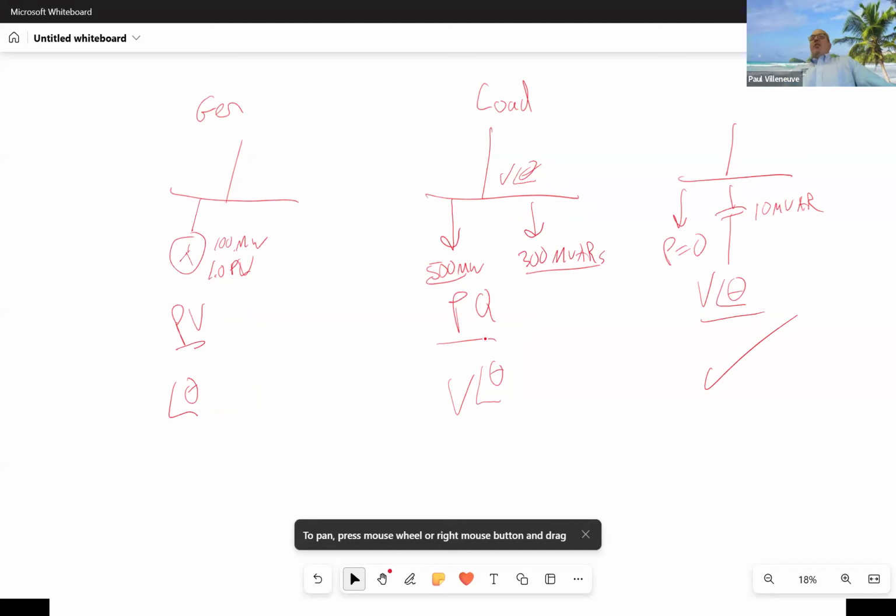Great question. So if you're designing a system, how do you pick the bus? Well, there's a couple ways to look at it. First off, you have to have a reference bus to pick up the slack. So you have to have a 1 at an angle of 0 bus because you can't perfectly predict the system. Usually that is a really large nuclear plant, something that can pick up all the slack in the world and doesn't have any problems. So that's usually set based on you're the big boss and you dictate what the whole system is.